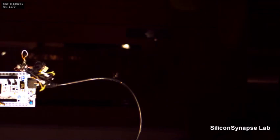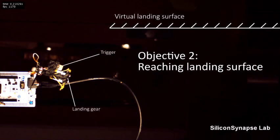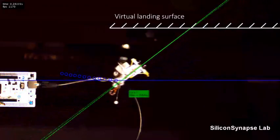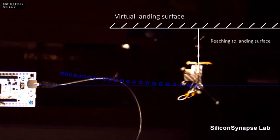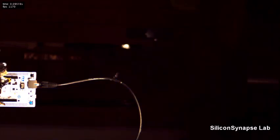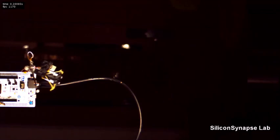The framework was tested in a series of experiments devised with an off-board computer, motion capture system, and high-speed imaging equipment. The computer automated releaser mechanism releases the robot with zero angular momentum in a free fall configuration, while the motion capture system captures the body and appendage orientations. The commanded angular velocities of the bob are resolved off-board and transmitted to the robot for the desired body orientation.